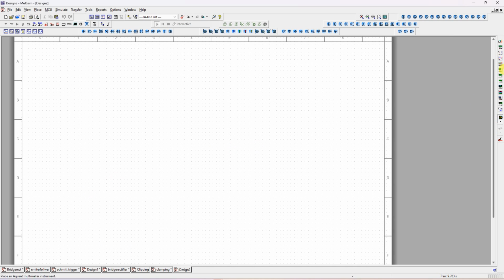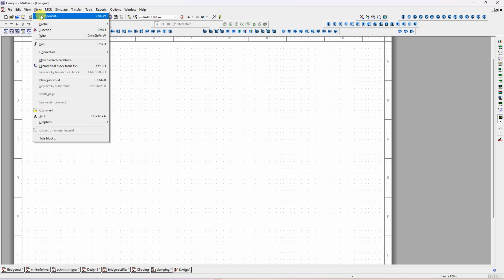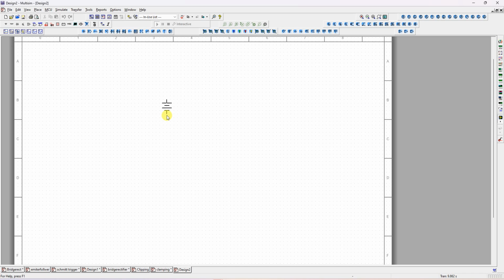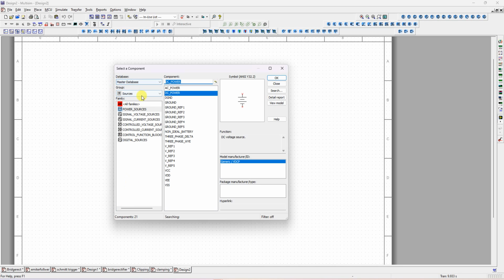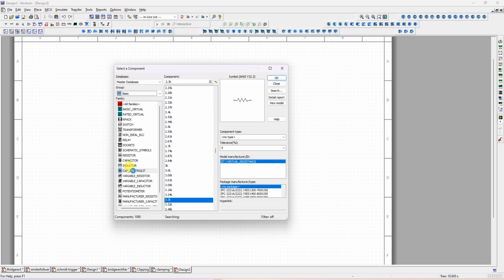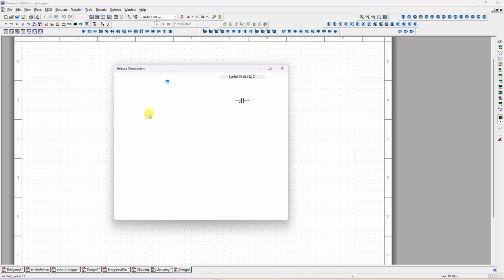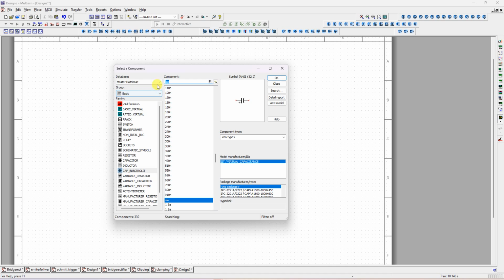Okay, so now let us do this. First, go to place component, select... I want one DC source. First, without reference voltage, no. So let me not take this one. Let me take only diode, capacitor. It is there in the basic. Let me take capacitor. Next, you take one diode.